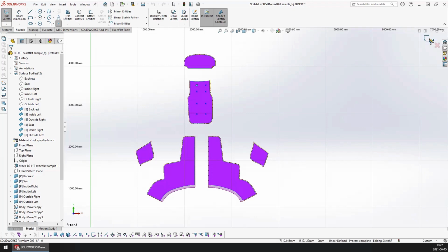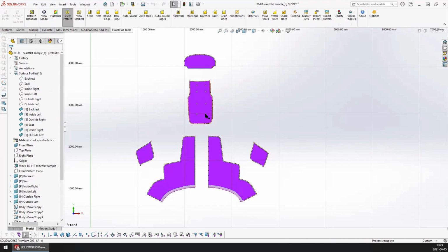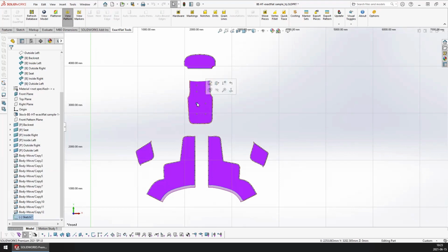And now that my sketch is done, I'm going to close the sketch. So now we have our sketch here. We have our 8 buttons, and it's in context of the pattern piece. We still need to map this sketch to the pattern piece and effectively register this sketch so it will be included as part of the DXF when we export our DXF pattern. To do this, we just want to make sure the sketch is selected. So we've selected a sketch down there.